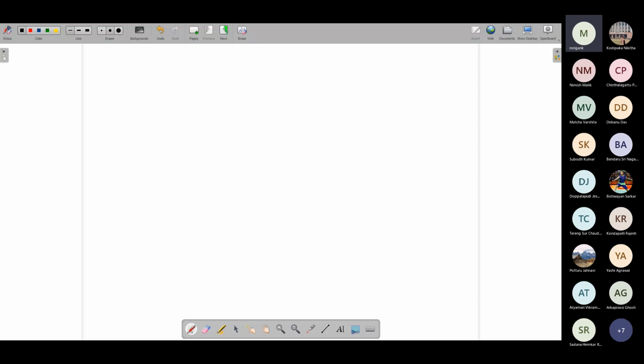So far, we have only looked at common source. We have looked at the variations of common source, different kinds of loads. We have looked at the cascode load, and there also we arrived at a high gain common source amplifier with cascode load. We also looked at folded cascode. So single-ended amplifiers we have looked at; basically, the variations of the common source configuration.